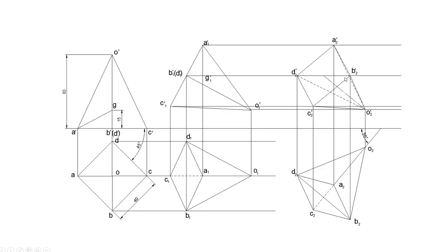Now here you have the border. Since the base is coming this side, here the base will be visible. This is the front view, so the observer is viewing this object from here. So on the observer's side the base is coming, towards him. So in the front view, the base is exposed to the observer, so the base is visible in this case.